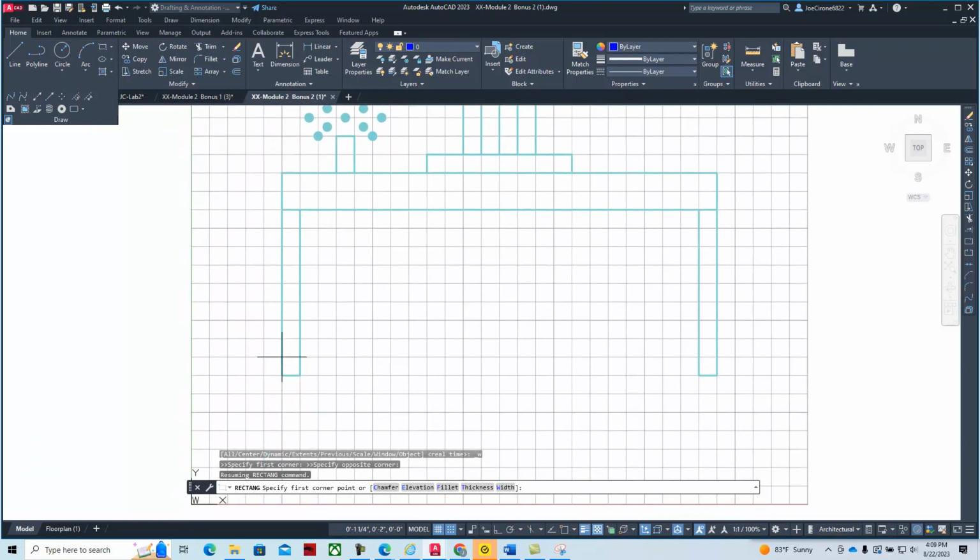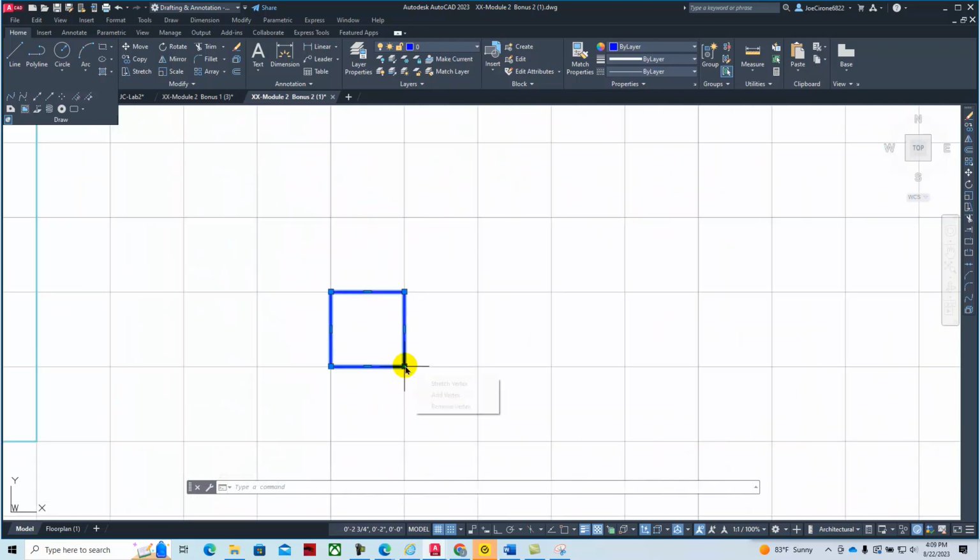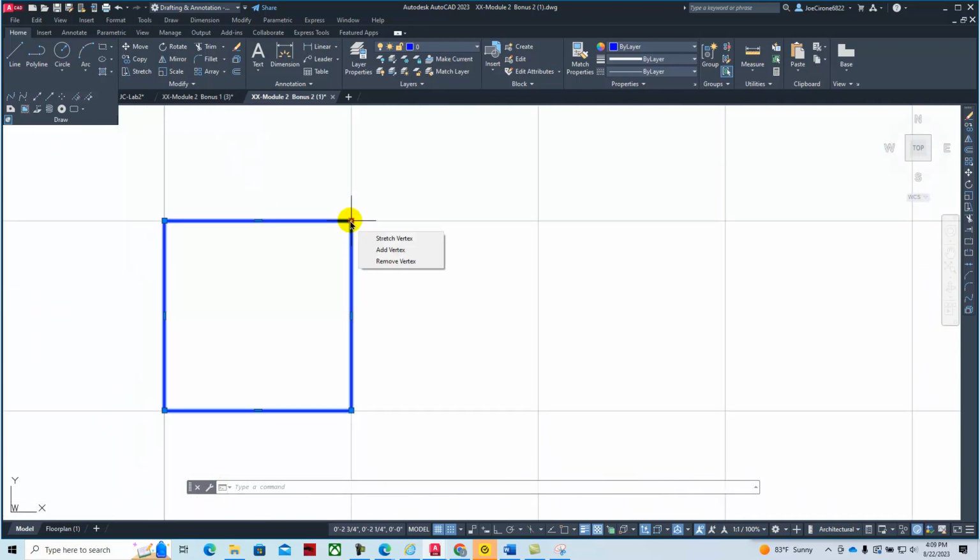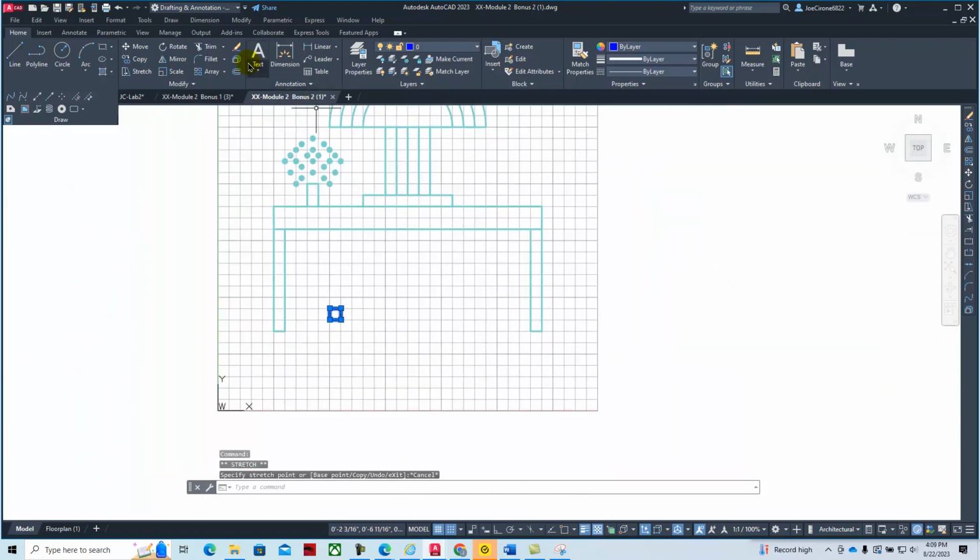As you see my cursor move, you can see that it snaps twice to every grid, because each grid is 1/4 of an inch. If I were to make a small square and click on it, these are called grips. If you hover over a grip, you'll get drawing information about it. Alrighty, and we can then erase that. So if we start off by creating a rectangle, we can bring it over here, bring it up, and click. We're drawing on layer 0, and it's blue.